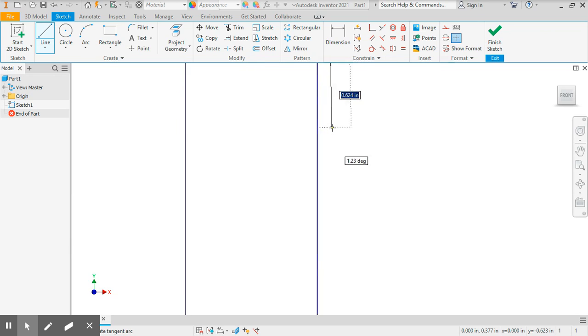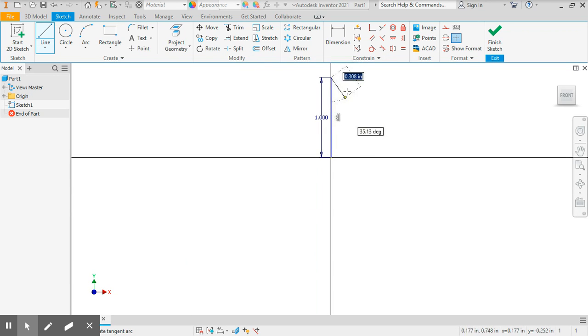Using my mouse button, I can zoom myself in and out, and I can see the end of that. And let's make another one that's maybe 1 inch long again. Hit enter. I can pull that straight down, and it's going to snap to that x-axis. I'm just going to finish that by dragging over. Notice I didn't have to put in 1 because we already defaulted to the origin or the x-axis again. If I click on that, I've got a square drawn.